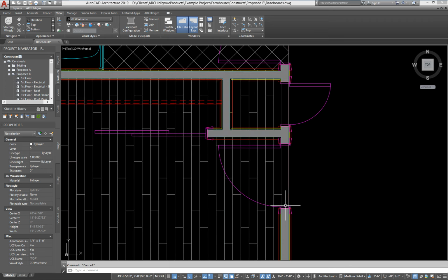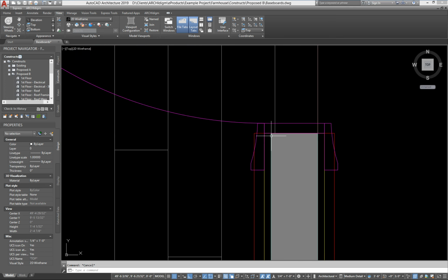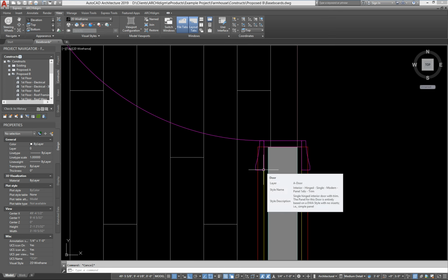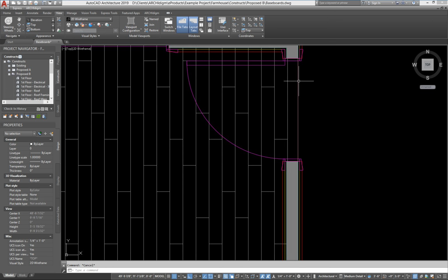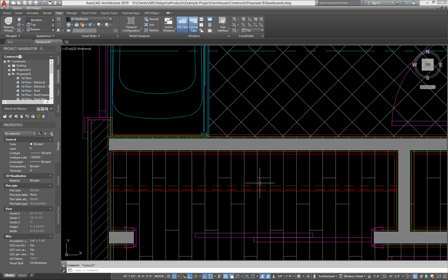Now if you want to make something like this work, let's say you don't have bathtub issues, or you're mostly only worried about rooms like bedrooms, you can define or create a wall opening end cap style that has the amount of offset that's required here. So you would have 1, 2, 3, 4, and 5 components to your end cap. And you could design that so that these things would be pushed back, but it would only alleviate this particular issue. It wouldn't address stuff like this where it goes behind the tub and goes in places you don't want it.